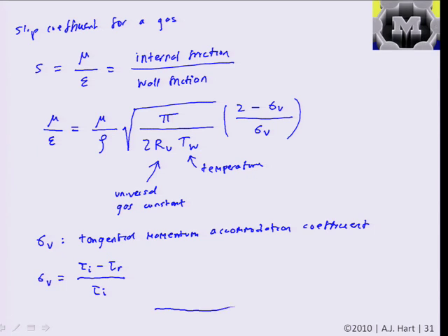And let's think about that physically in a couple of limiting cases. One where the gas molecule comes in at some incident angle and hits the wall and basically reflects perfectly. This is like specular reflection of the gas molecule. So this is the case where we'll say the reflection is specular and the tangential momentum accommodation coefficient is 0. So here is where we would have the most slip.